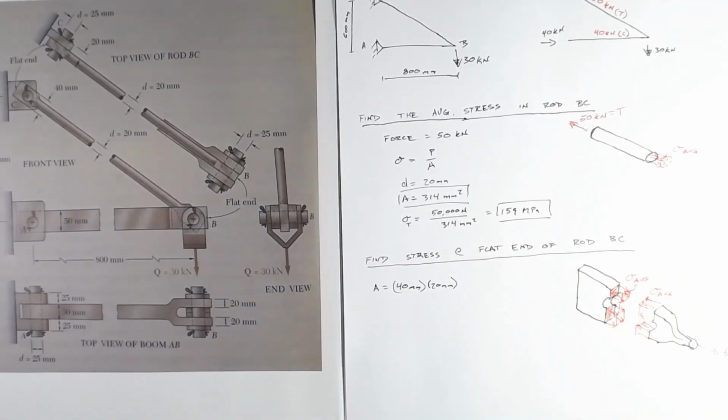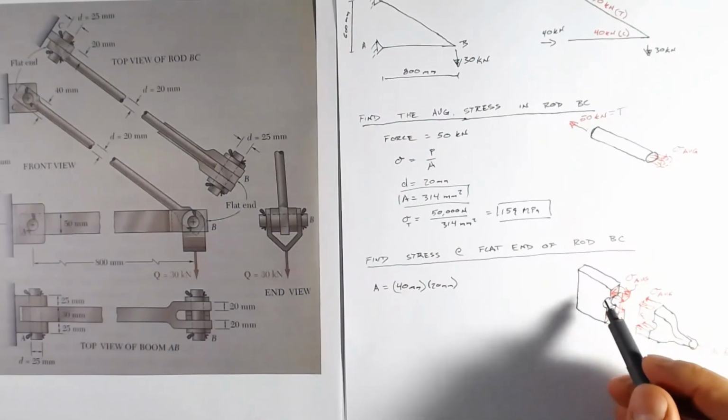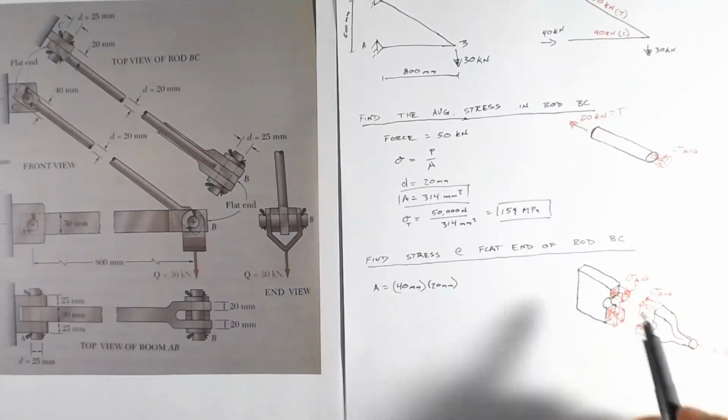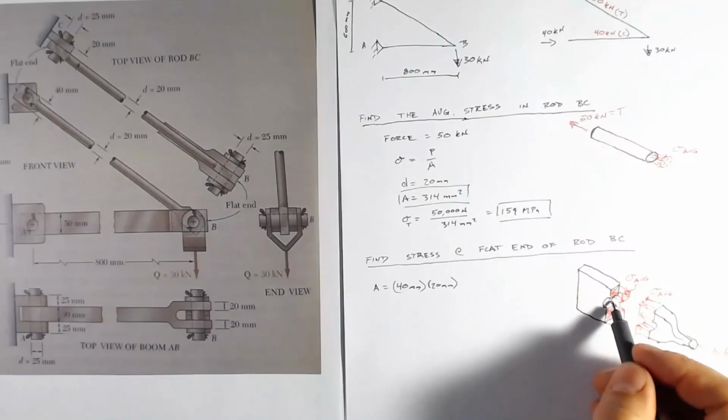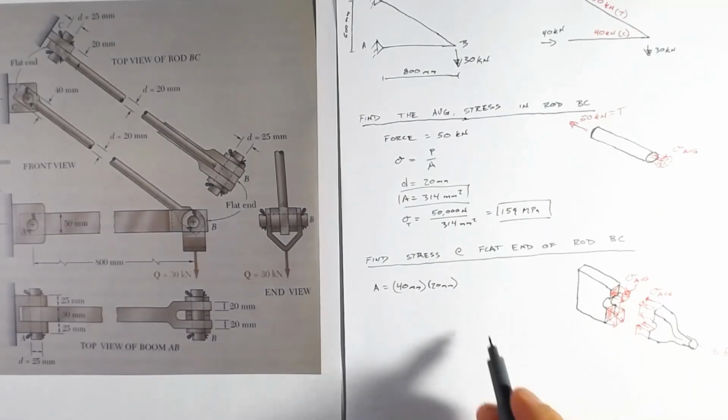Now, if you remember back to when we were talking about bearing stress, we have this hole out here, but this curved section is not in tension. We're only taking out this projected section here. So all we need to do is subtract out the diameter times the thickness. You can think of it like this little square which is missing.